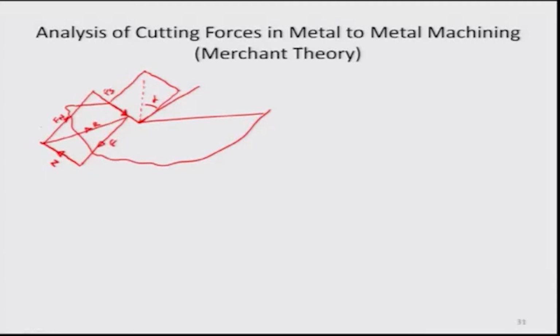And obviously, there would be a third cutting and tangential force which would be offered by the workpiece onto the tool surface, because the tool is having a ploughing motion into the workpiece. Okay. So, having said that, obviously, the normal force on the shear plane due to which the normal stress would probably come up is because of this Fn value right here, and the area of the zone, I think, which we had done earlier, was actually W t1 by sin phi.